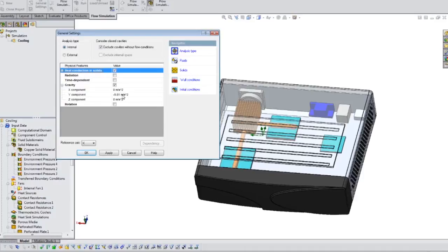The next piece there is steady state and transient analysis. Again, most of the time, the work that I've done here at Hawk Ridge Systems, people are looking at what happens over a long period of time. But there's also components and understandings that you may want to have around what happens over a specific period of time. So for example, talking about our electronics cooling, we may have an electronics enclosure that we turn on at T equals 0 seconds, and we want to ramp up the heat from 0 to 10 seconds, and then turn it off and see how long it takes for the system to go back to a stable environment. We could use a transient analysis to figure that out.